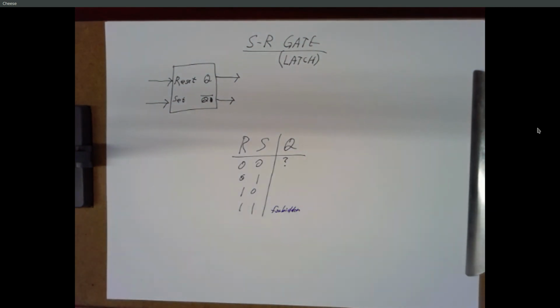Can I put VCC on the other end of the LED instead of having it go into ground? On the other side of an LED? No, never mind. I was thinking it would just light up if you have a 0, right? Yeah. Put the LED backwards, put VCC on the other end, and then it lights up for 0.